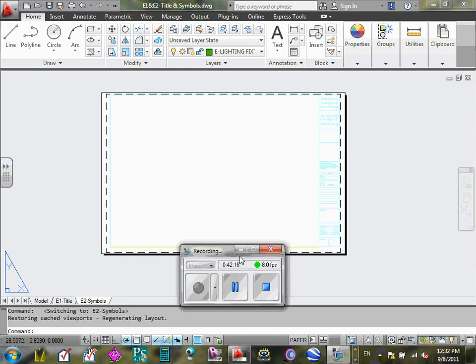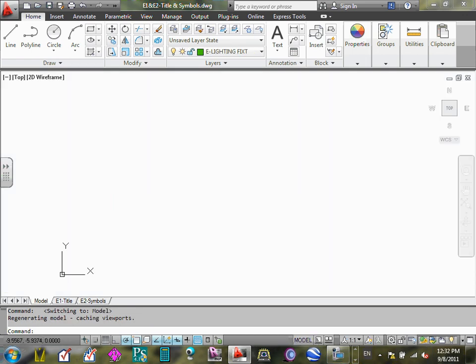Okay, the second thing I'm going to do, so we did that one. In here, there will be 2 things. Number one, there will be text. You can start any text and write whatever. I'll give you a few texts as we go through, so leave it empty for now. The second thing are the symbols. For symbols, when I have a list of symbols for you guys to use, we do not XREF them. We copy and paste them. Why? Because as we go through, you might have to delete, add, subtract, modify the symbols. If they're XREF'd, it's hard to modify them, but your symbols, you should have full access to your electrical symbols where you can edit them right in the spot.